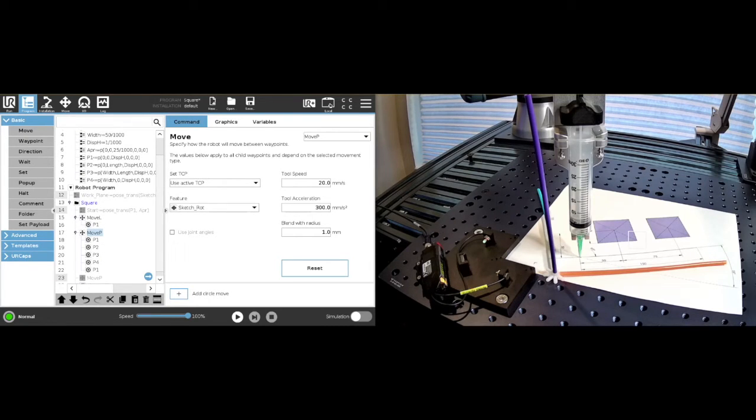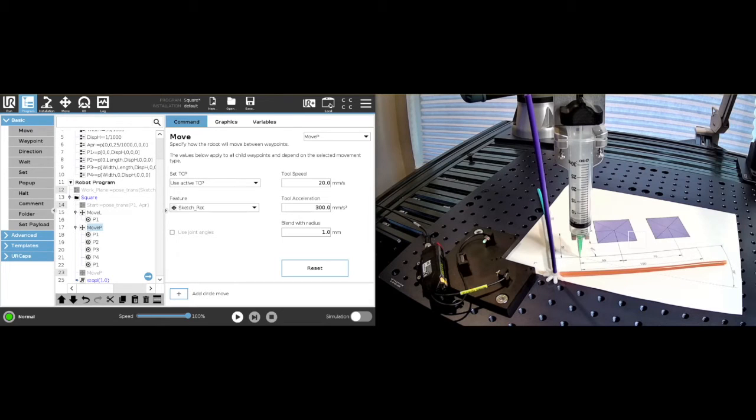We're going to define an approach, which will have a 25 millimeter offset in the Z direction. So we're going to define this variable APR, like this. So here are our length, our width, our dispense height, and our 4 points. Okay, so now what we can do is say we don't want to start at P1, but we want to translate P1 by that approach point.